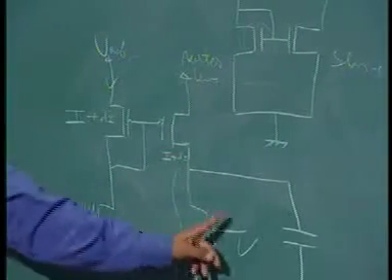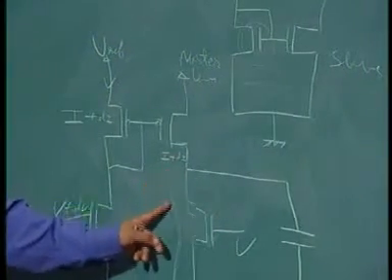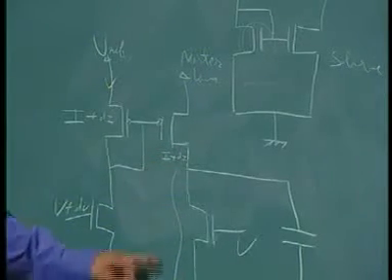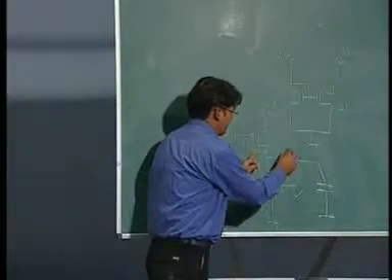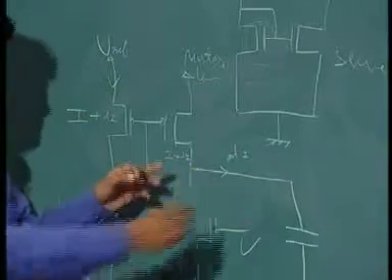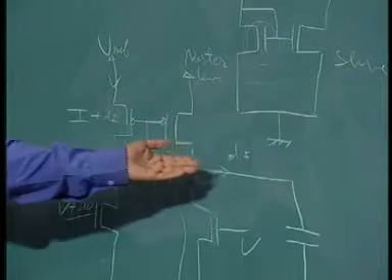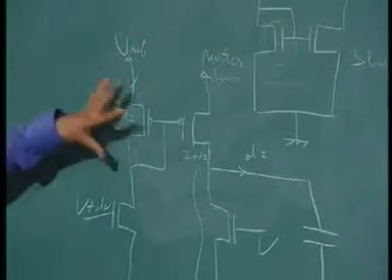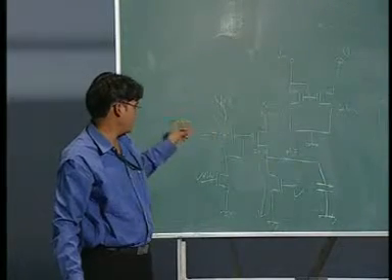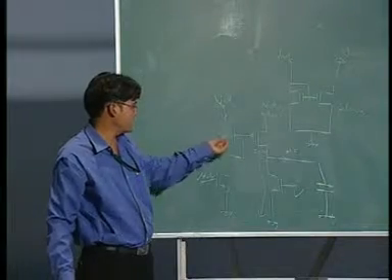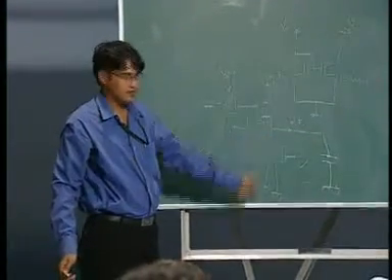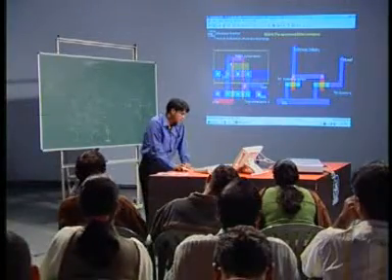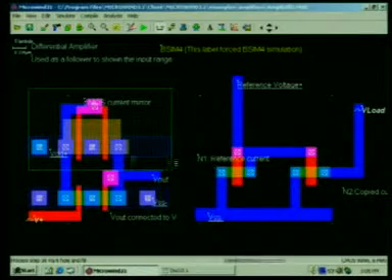But since I have applied V voltage here, the driving capability of this NMOS is only I. So, that I current will flow here, but the remaining delta I, I can get at the output. So, this can be amplified. So, this is the differential amplifier concept. Using the current mirror, I have utilized that dI current to charge that capacitor load. So, based on this one I have created this one.